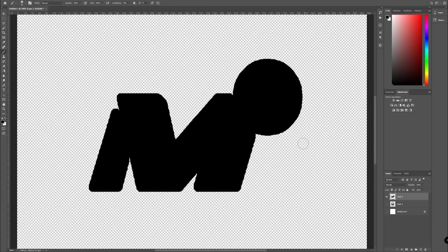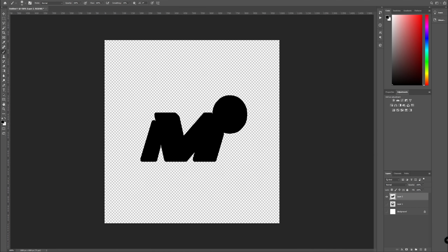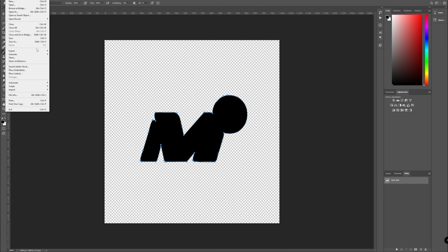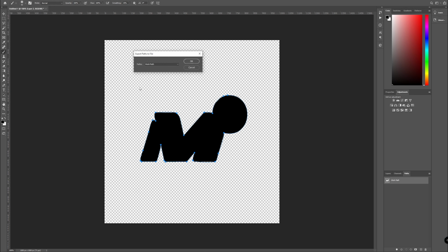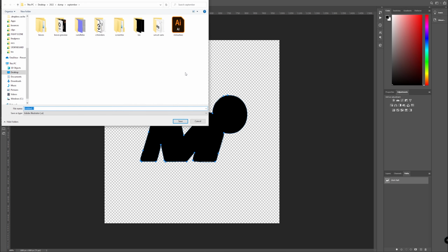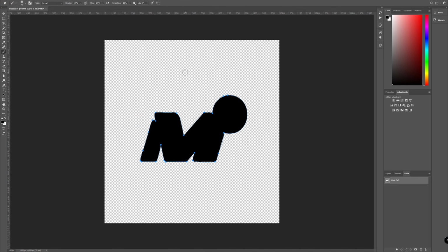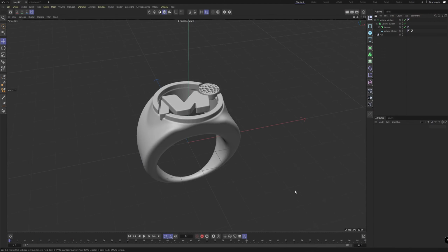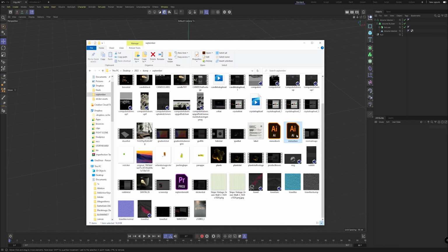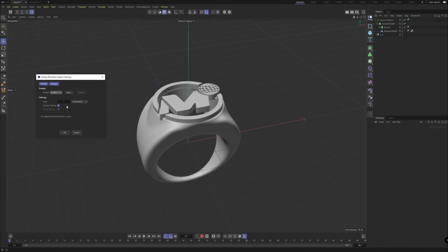We can untoggle this, and this is going to be our little backbone piece that we can export into here. So control click on that, path, same thing as before, export your work path, head to file, export, paths to Illustrator, okay. Minus 2 back, click OK, and pretty soon we should be able to get to the rendering part, so we can locate that super quick, drag the minus back in here, hit OK.